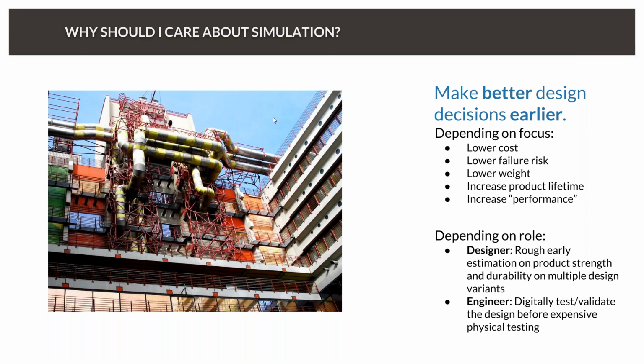So everything was based on rule of thumb. And what happened in the end is that they finished the hospital building, and after some weeks they found out that something was completely wrong with the HVAC system because it was much too hot inside the building. It came out that the whole HVAC ducting system was under-designed. So all the ductings were too small.